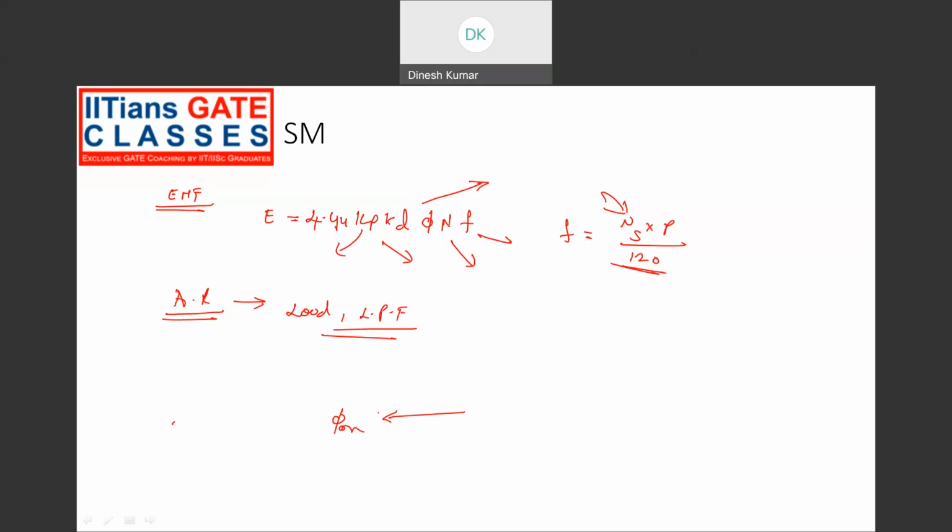On the rotor, because of this flux, since the rotor is rotating, there will be an EMF induced in the windings on the stator. That EMF will lag this flux by an angle of 90 degrees. Now let us consider that on the stator we have a resistive load. The stator winding is connected to a resistive load, and that's how the closed path will be completed. So the current flowing through the stator winding will be in phase with the induced EMF because it is a resistive load. IA is the stator winding current, that is nothing but the armature winding current.